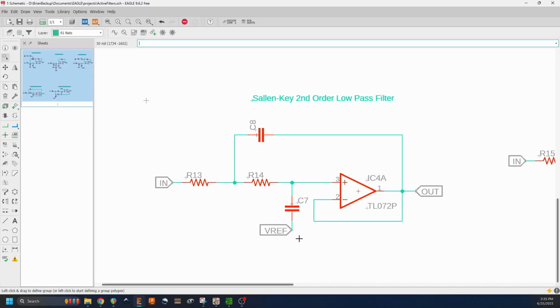It determines how much the filter rings. There are a lot of really technical, in-depth parameters that you can control more tightly with the Sallen-Key topology than with 2 cascaded RC filters.